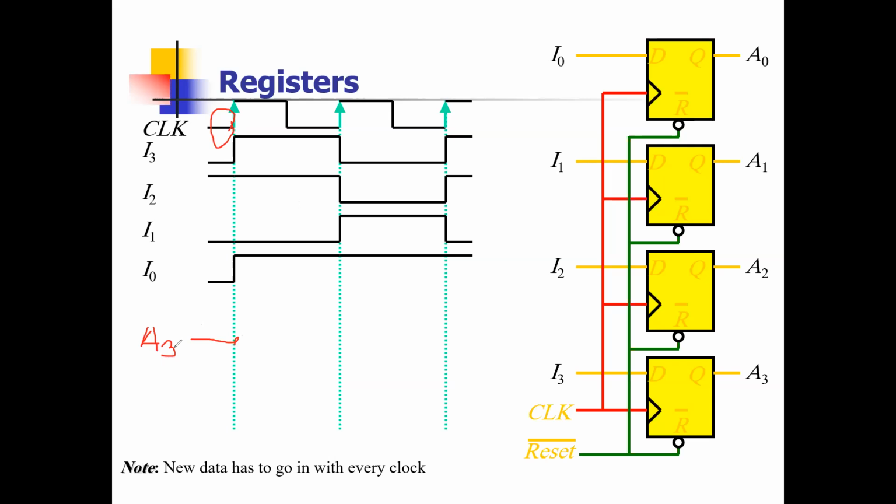Now it is the time where the result will change because I am getting the clock here. If I check I3, I3 has 0, and I3 has 1, meaning there are 2 values for the same clock. So tell me which value I need to choose. 0. Why? The beginning is 0.